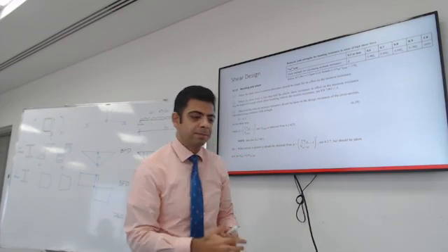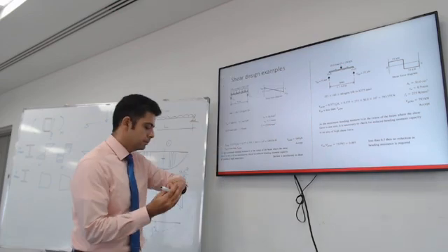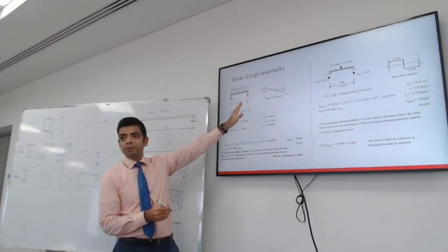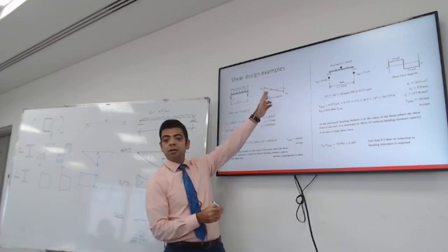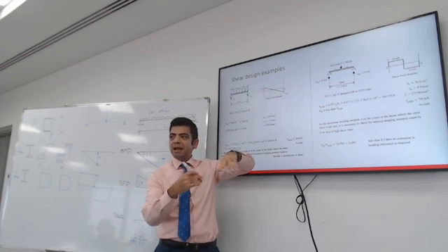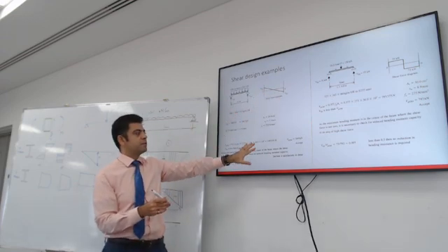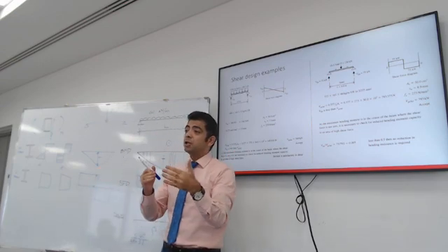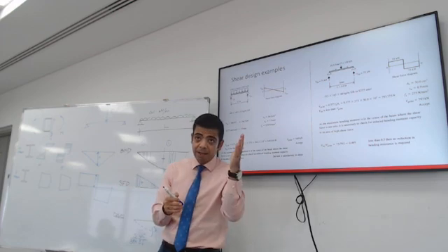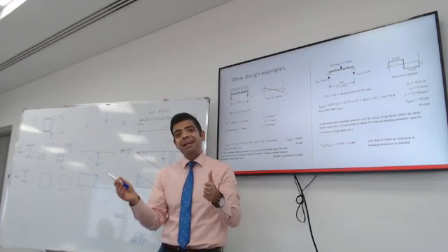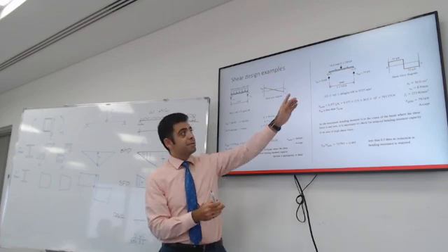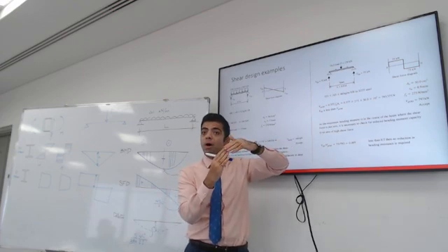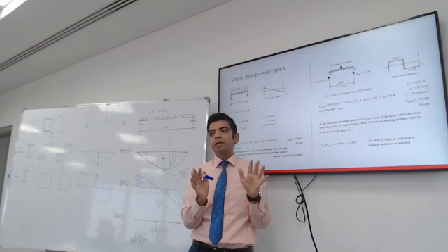So let's take an example. This is a beam with a distributed load. Maximum shear is not at the same position as maximum bending. So I just apply the formula and say checking bending and shear together is not necessary there, because maximum bending is at a different location from maximum shear. At this point load, I will have to check that. In my case, the ratio was less than 0.5, so no reduction needed.